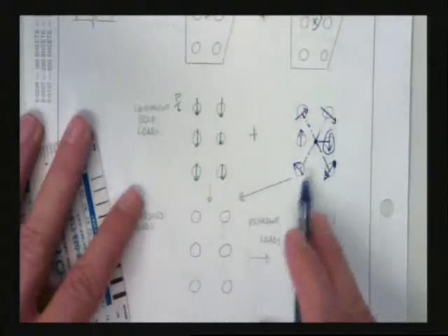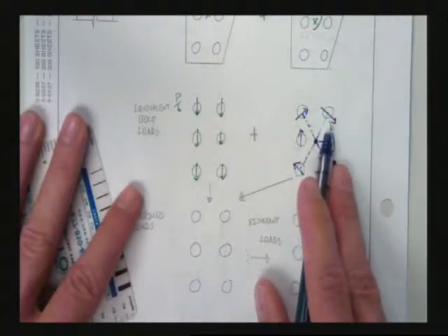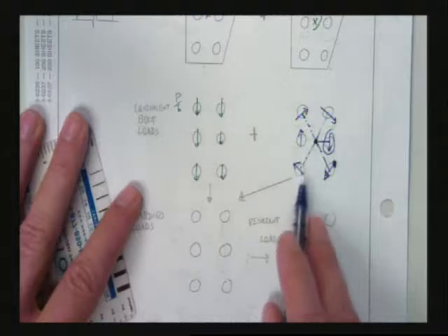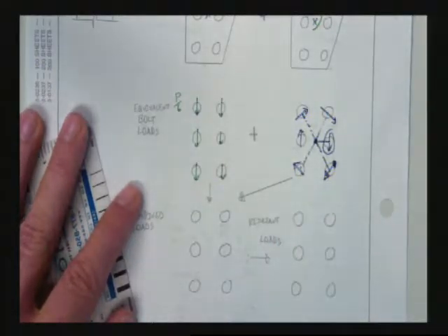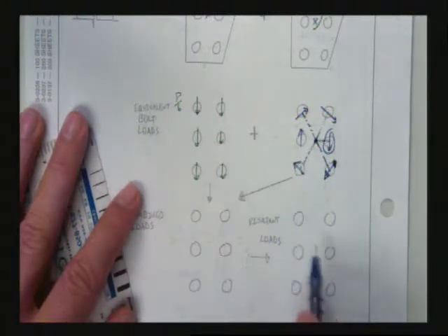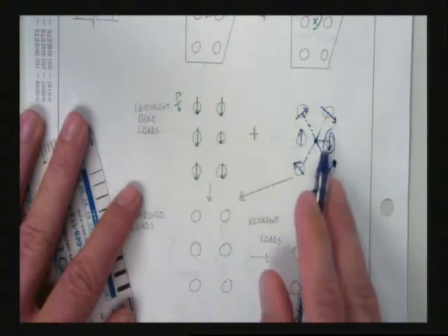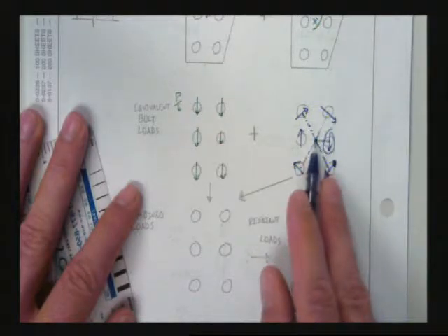Now I ask this question. What is the magnitude of each one of these force vectors? What do you think? That's a hard question. Not a very apparent answer. We have to give more of a rhetorical answer. And the answer is that it's actually a function of the distance from the center of stiffness. At least elastically. That's the way we always work the problem, right?